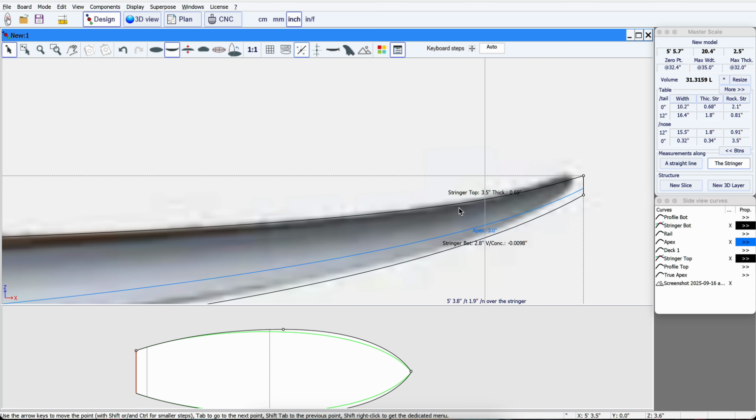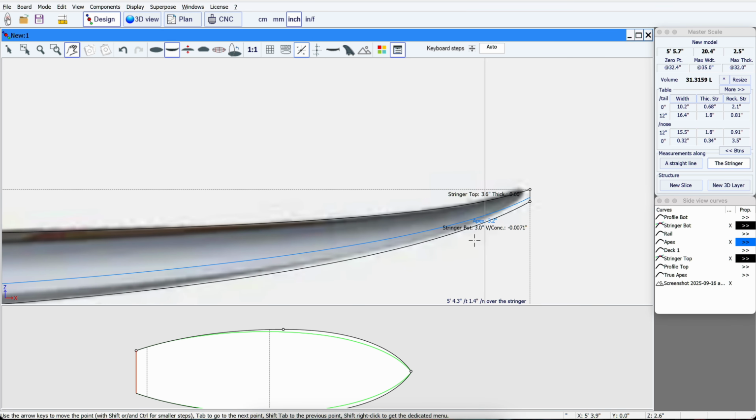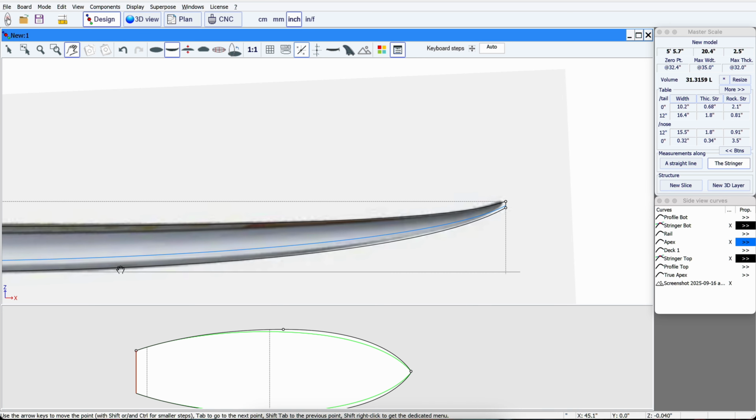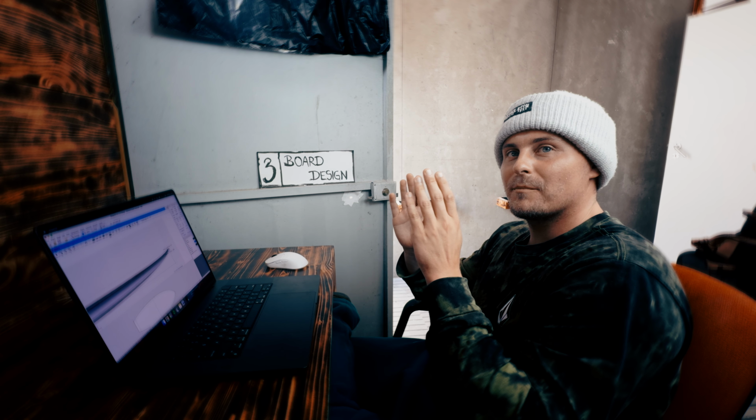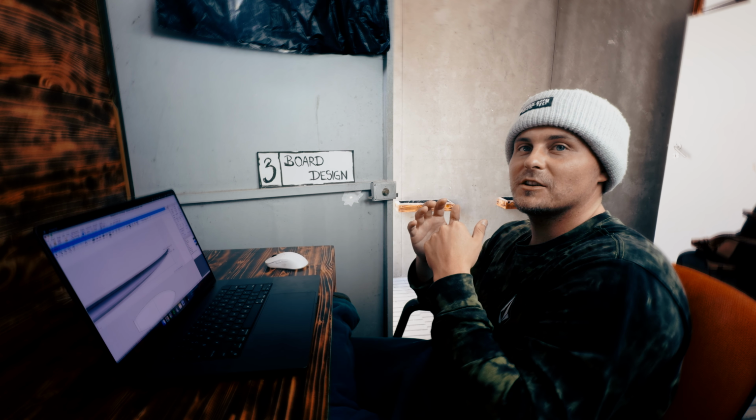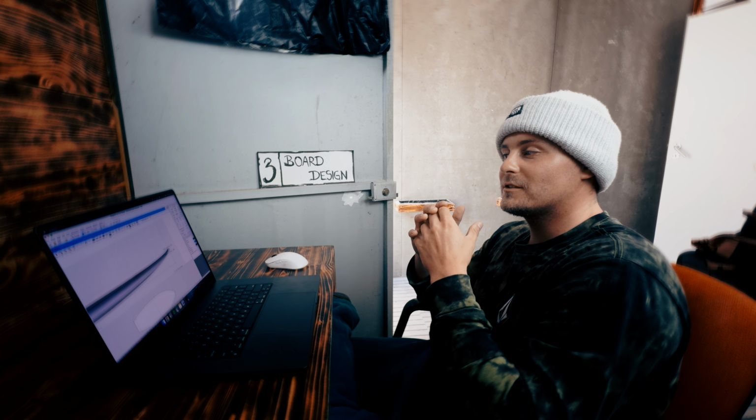Do not be crazy to do this here on the cut, as it's better for you to leave yourself kind of 0.34, even sometimes 0.40, this thickness of the nose, and use this as your rocker when you're shaping the rocker, and then just by hand flip this part. Like this last 2 inches that you're gonna be flipping by hand, that's gonna change your, let's say, nose rocker on the 0.0. It's not gonna change the way the board works, and in most times it's really just a visual aspect to thin out the nose. So do not really be crazy about that.